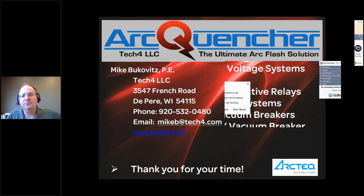But in terms of the time needed to install in an MCC, we've done a lot of this and retrofitted MCCs. I'll be very frank here. Motor control centers are the most complex piece of equipment on which we install arc flash sensors. We use a combination of point light sensors and fiber light sensors in the motor control center, and it does involve removing the buckets, because we have to.